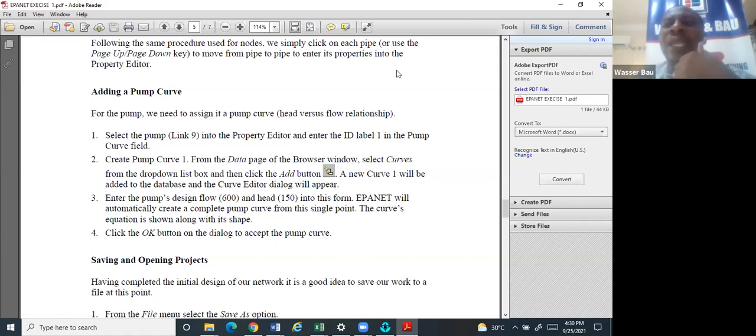Now, we are engineers. Every pump requires a pump curve to run. When a manufacturer produces a pump, he calibrates it based on the pump curve, which my colleague taught us on the first day. The pump curve will tell you the best operating point in terms of the efficiency, the flow, and the head.